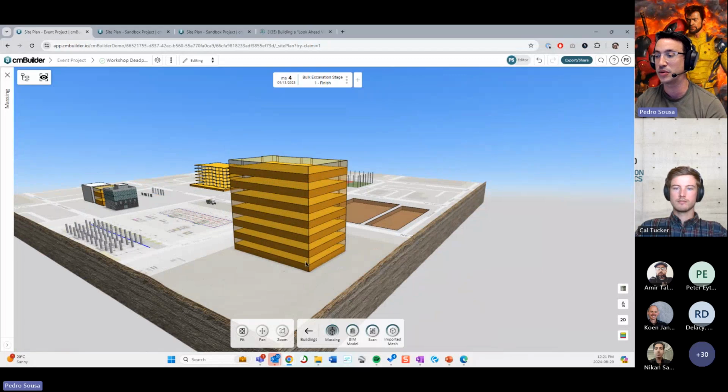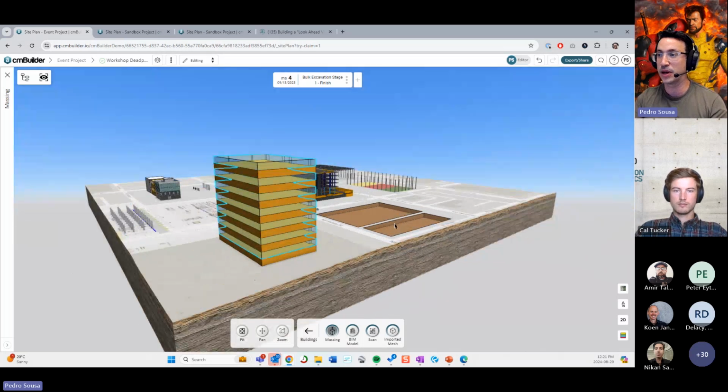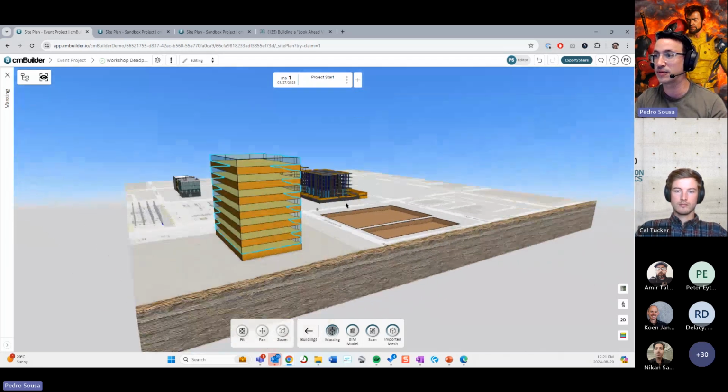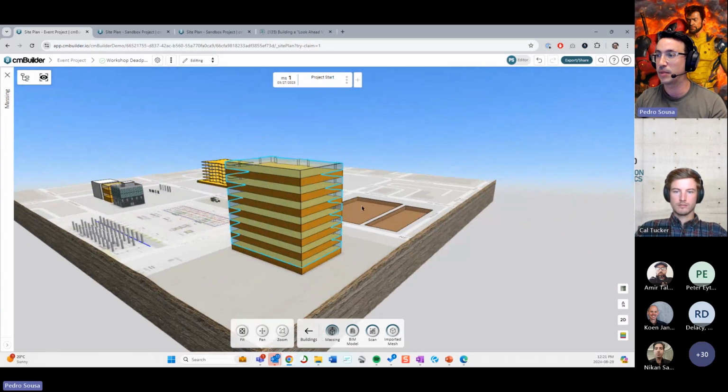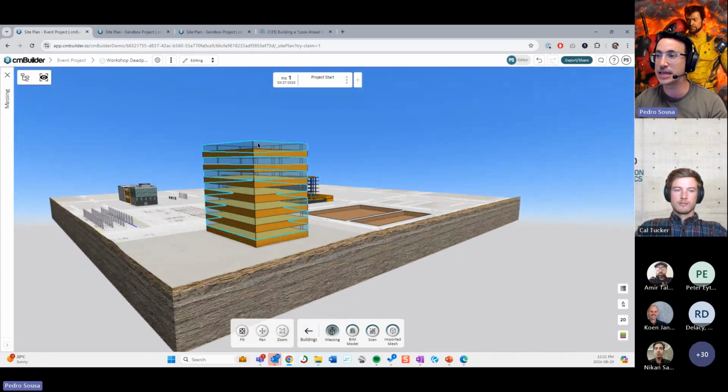So what I'm going to do is take all the transparent levels, select them all, holding control, and then go into the first milestone over here, maybe the second one. I know the milestone where everything showed up. Yeah, the first milestone over here, and I'm going to hide these objects on the first milestone, right?